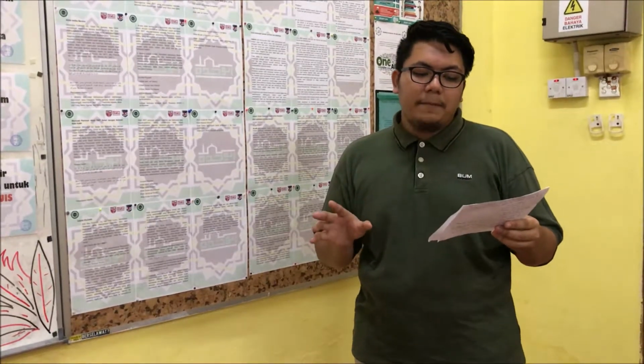The first step is to list the parameters in the problem and count their total number, which is represented as n, and list the primary dimensions of each of the n parameters. The third step is to set the reduction j as the number of primary dimensions. Calculate k, the expected number of Pis, where k equals n minus j. Step 4, choose j repeating parameters. And the fifth step is to construct the k Pis and manipulate as necessary. And the last step is to write the final functional relationship and check the algebra.